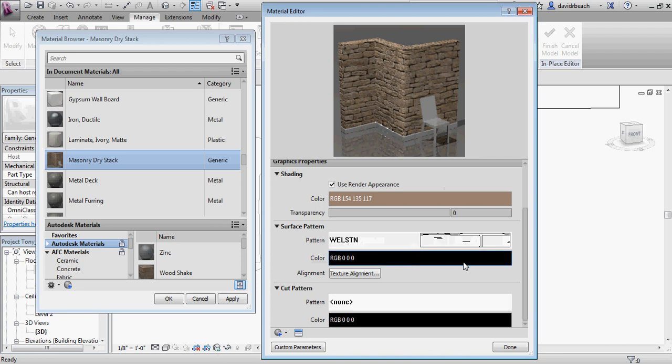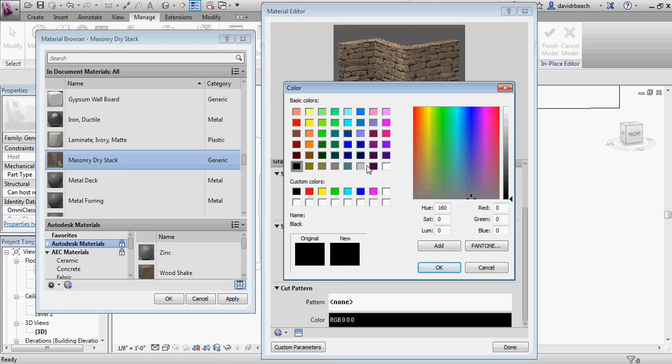On any hatch pattern that I use, this is a personal preference, but I really hate using a hatch pattern with a black line. In my opinion, a hatch pattern is usually secondary information. I want it to be background in the drawing, so I'll usually set it to this sort of medium gray.